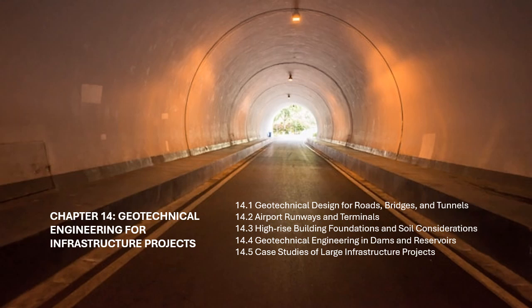Inclinometers and tiltmeters. These instruments measure the movement of the dam and foundation, allowing engineers to detect any settlement or tilting that could indicate instability. Seismic monitoring. Seismic sensors are installed to measure ground motion during earthquakes and assess the impact of seismic events on dam stability. Visual inspections. Engineers conduct regular visual inspections to check for signs of cracking, erosion, or other damage to the dam structure.